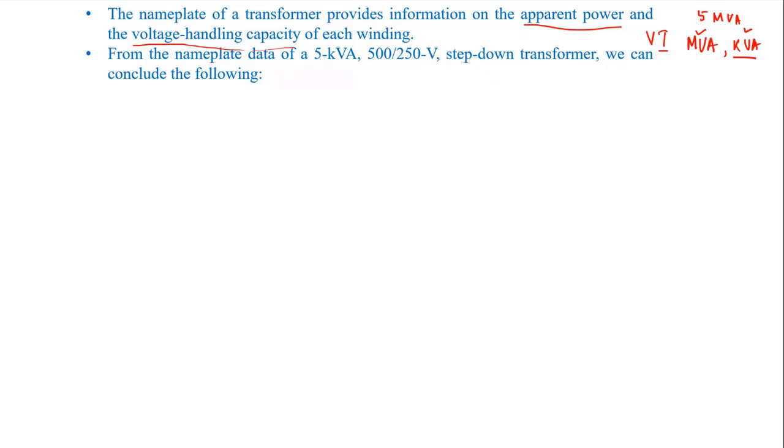Like in the main substation you'll find 33 kV by 11 kV, right? So the high voltage side is connected to the source and the 11 kV side is connected to the load side. And then again the 11 kV is transformed using step down transformers, 11 kV to 440 volt. We have many substations around the campus.